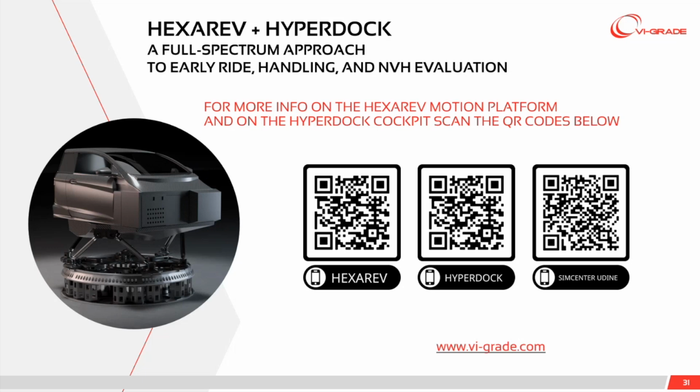These hub accelerations are sent to the VI and VH simulator, which is calculating through transfer functions the accelerations at each touch point, be it the seat rail, the heel plate, or the steering wheel. But in reality, this is completely tunable, meaning that if you have additional transfer functions, you can define additional inputs to the VI and VH simulator.